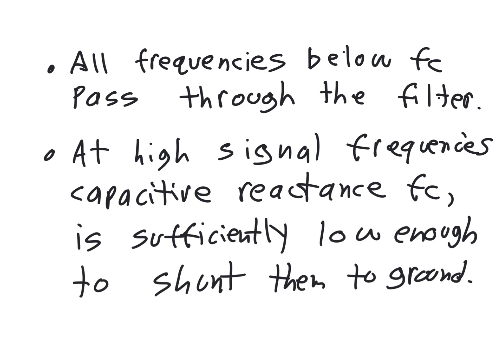So again, it all hinges on the reactance of the capacitor. When the capacitor reactance is high, the signals pass through the filter. When the reactance is low at the higher frequencies, then those high frequencies are simply dumped to ground and are attenuated. Okay, so those two components is actually what's doing the filtering.